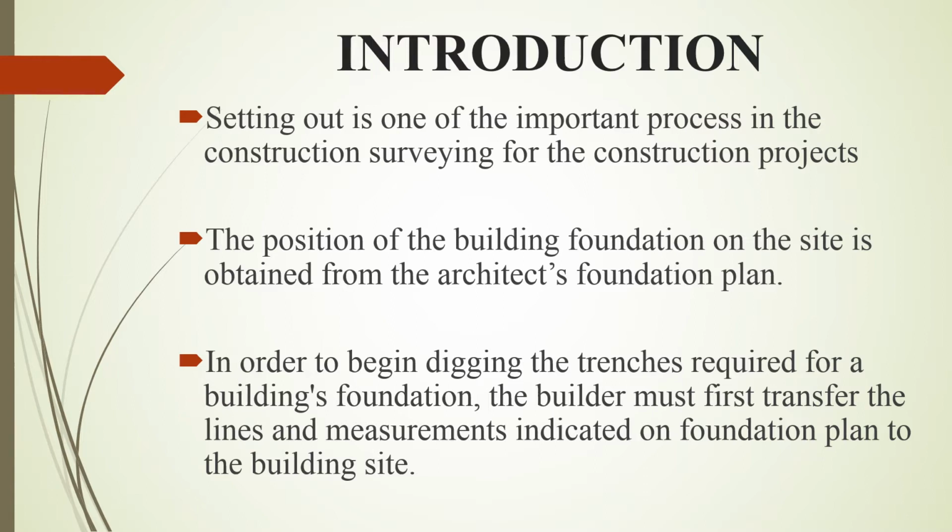In order to begin building the foundation, the builder must first transfer the lines and measurements indicated on the foundation plan to the building site. That is, the exact length, width, depth, and position of the foundation trenches must be marked on the ground. This transfer from the plan to the actual site is called setting out. It's probably the most critical step in the entire construction process.